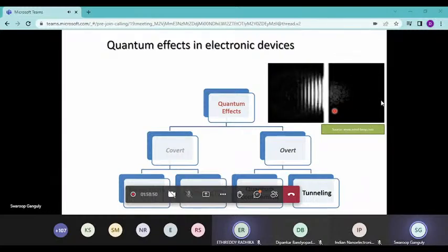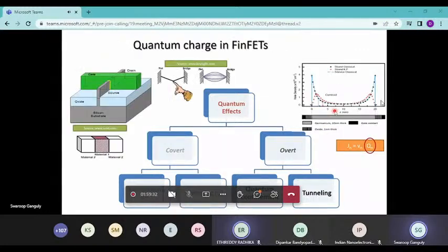And it is a problem in some situations in device physics, such as in MOSFETs, when your oxide becomes too thin and you have this kind of tunneling going on. That becomes very difficult because what is supposed to be an insulator becomes a conductor. But there are other contexts in which we are actually able to use the tunneling to our advantage, and we have come up with very useful devices that use the tunneling in this way. One example is shown here, the USB stick, which has flash memory inside it that uses tunneling for reading and writing. Okay, I'll move on and define for you now the problem which I want to solve by simulation.